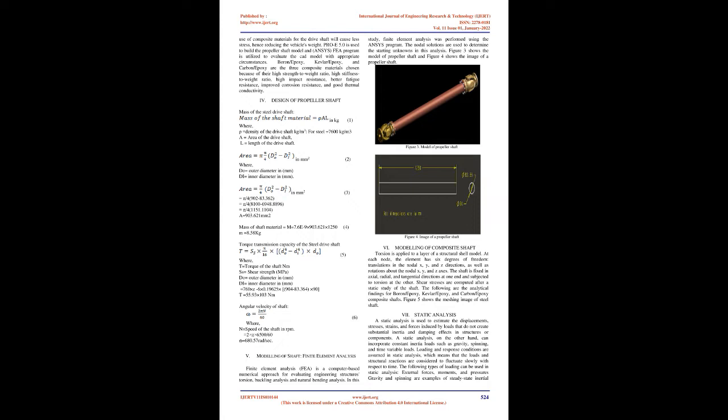Reddy and Nagraju, 2017, 12 investigated the design, material selection, optimum stacking sequence, and performance of composite drive shafts in order to compare the performance of composite drive shafts to steel drive shafts. The optimally designed drive shaft finite element model is created with the commercial finite element program Ansys. Static, free vibration and tensile buckling analyses were performed, which are essential for rotating parts such as drive shafts. Finally, it is found that across all evaluations, a weight reduction of 97% over steel drive shaft is attainable.